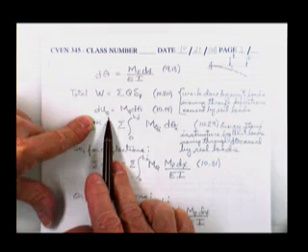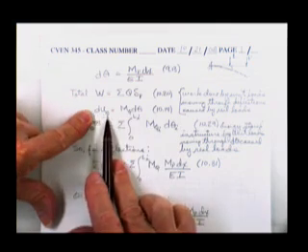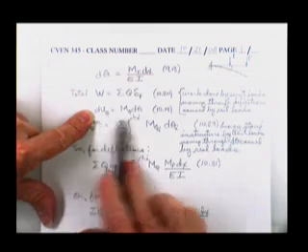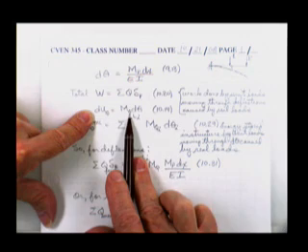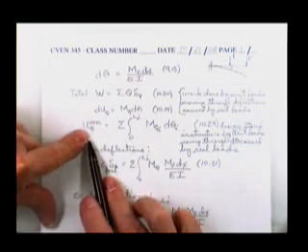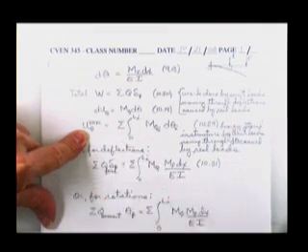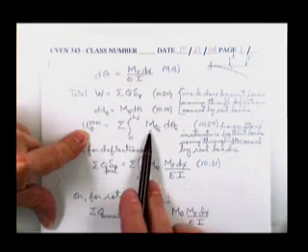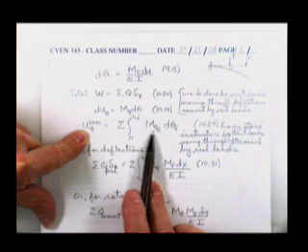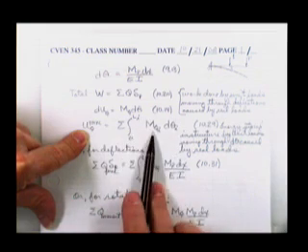If you bend something, the little bit amount of energy that you store due to a unit load is the moment caused by that load times how much theta it caused. The total amount of it, you'll usually have to integrate. Unlike trusses where the load is constant throughout the member, this number usually changes as you move around on the beam, so you'll have to integrate the term.